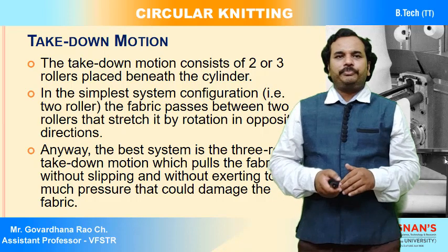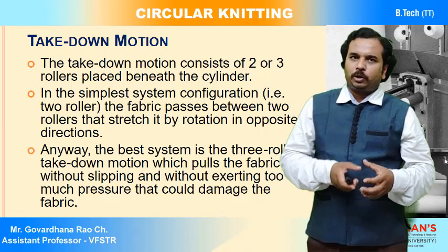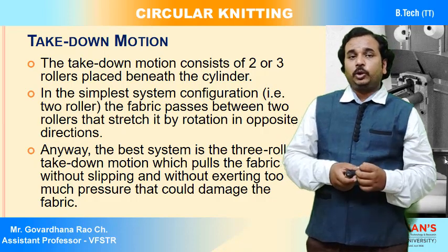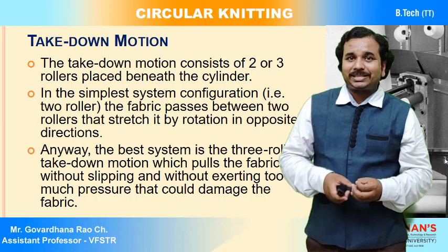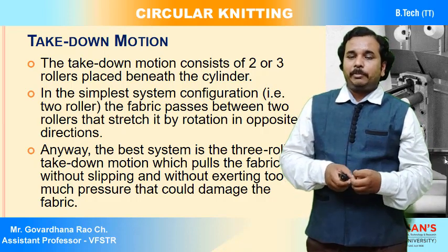The best system is a three roller takedown motion, which pulls the fabric without slipping and without exerting too much pressure that could damage the fabric.